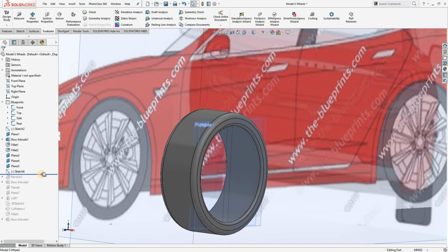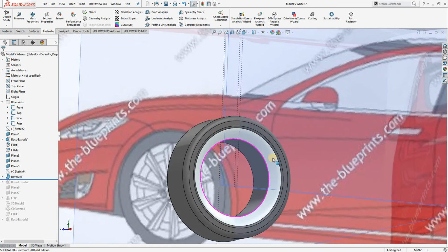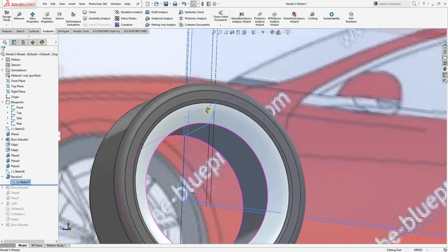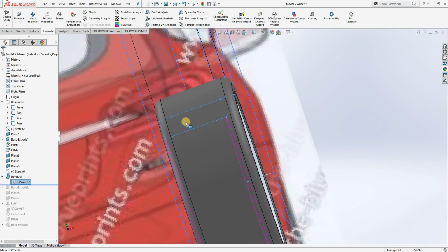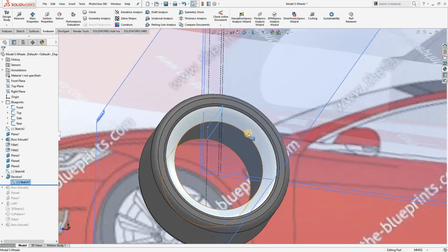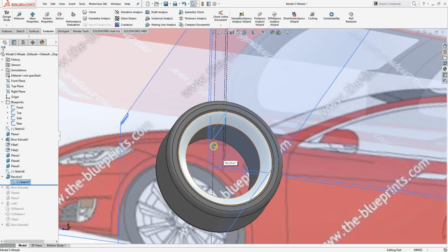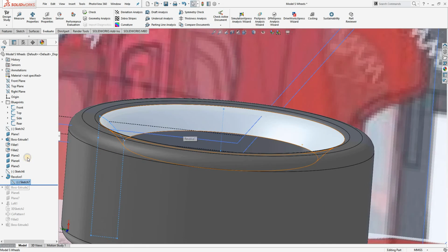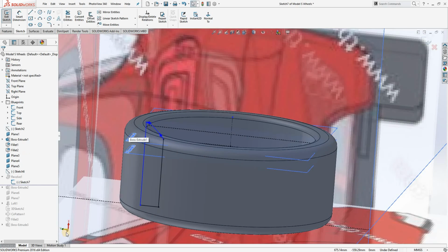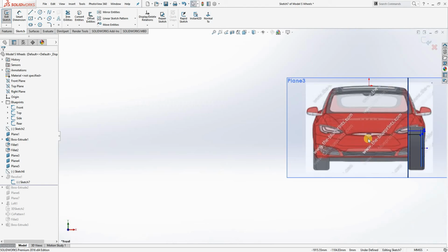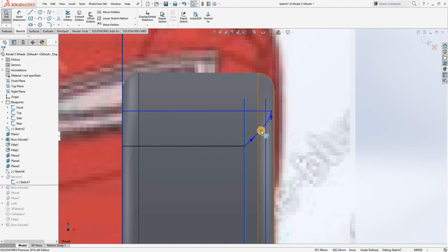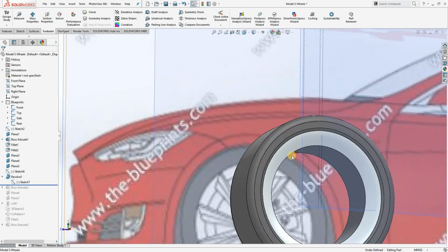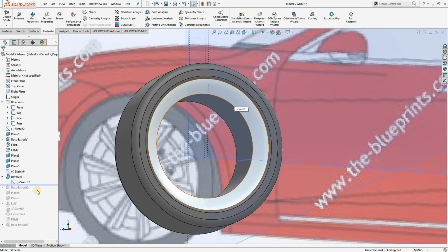And I started creating some planes. And I did a revolve, so I'll just show you the sketch for that. That sketch there, I revolved it around the circumference to create that shape. I'm sure I could have done that a different way. I could have done a fillet. Oh, actually, I wanted some curvature. I wanted that to be slightly curved, which is why I did a revolve instead of a chamfer, for example.